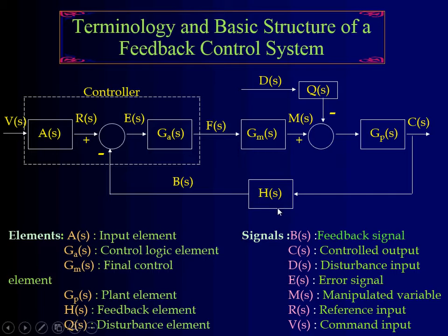And your setting here will produce a set voltage in here. That voltage, this voltage, or you could call it the reference voltage in here, would be compared to the one that you get from the system. And then the difference of this will produce an error. This is the error signal here.